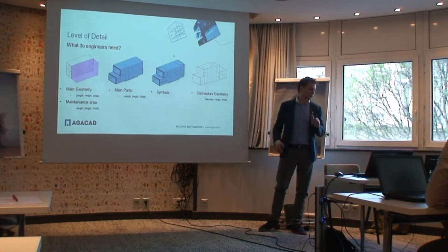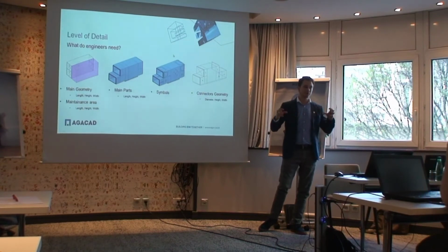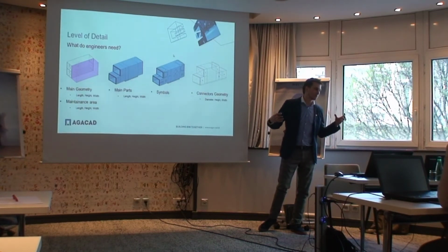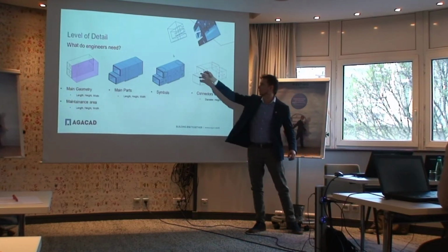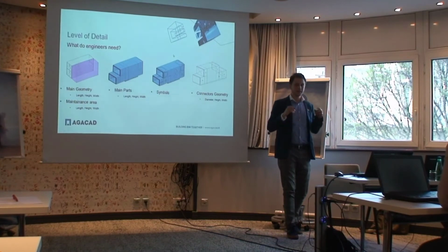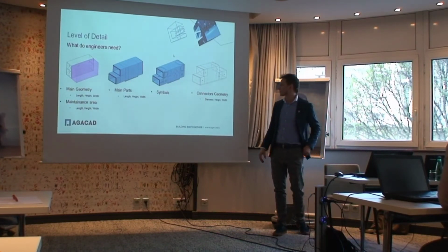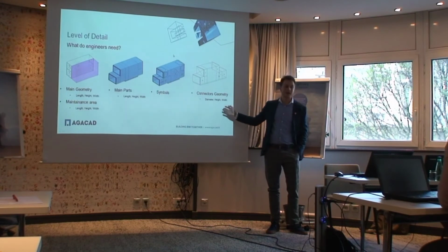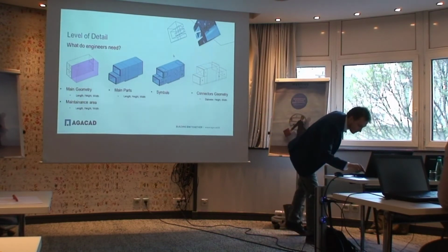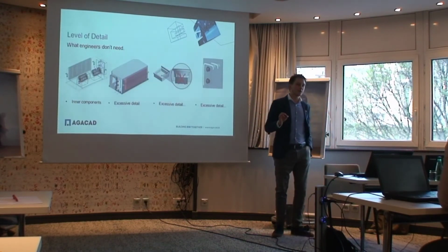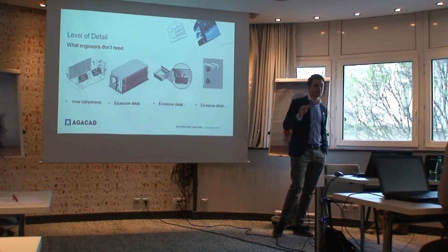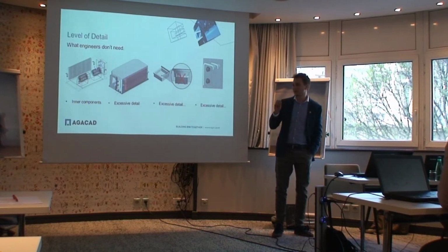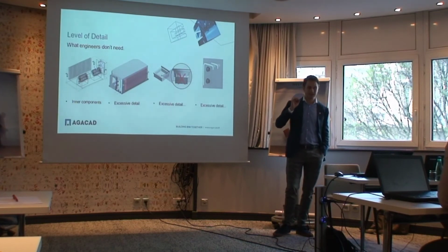As well, we need the connectors geometry, where and what kind of ducts, pipes, electricity we are connecting to the element. In my case, I have 4 connectors there. From that side, you can see the pipe connectors, electricity, etc. So again, we need diameter, we need height and width. Just to make sure, if you're going to get involved in BIM, you shouldn't create too detailed elements.